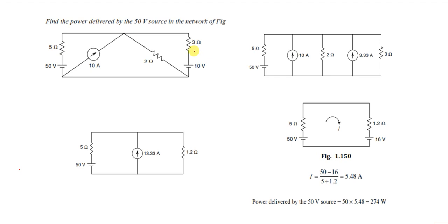This is voltage, this is R. So I is equal to V by R. 10 divided by 3 is 3.33, and always the arrow mark is towards plus. In the battery, you see here this is plus, this is minus. So you have to write the arrow mark like this in the current source.